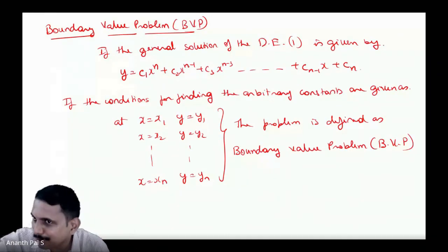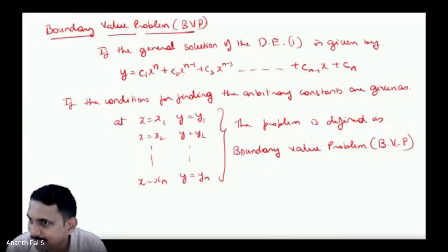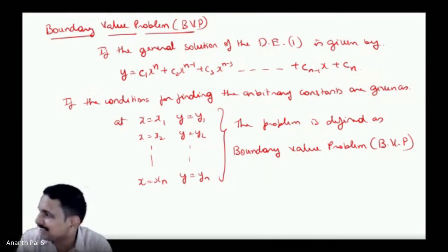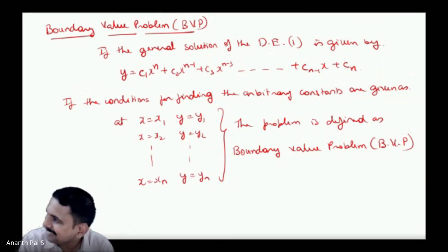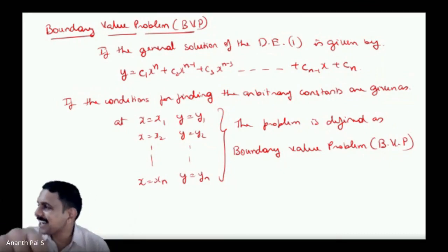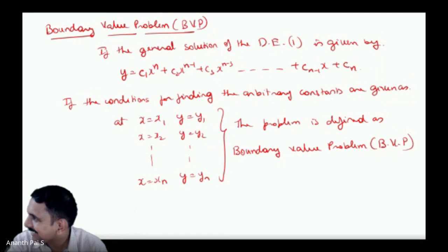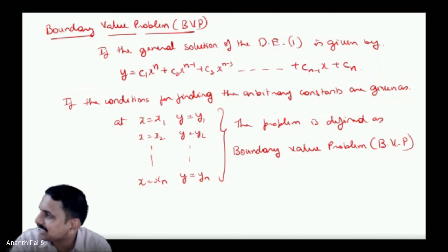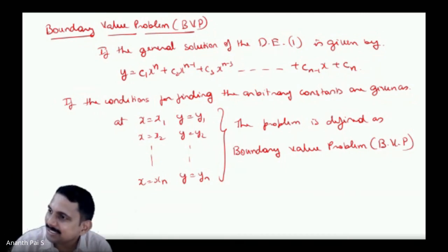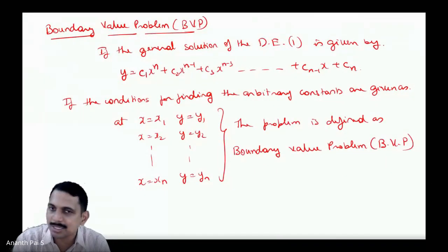If you go to AutoCAD, have you gone to AutoCAD? In a circle, you have 9 types of defining a circle. Center and two sides of a diameter, you define it. Center and radius you can define. Then tangent, tangent, radius. Point and a center, point and a tangent, something like that. There are 9 ways. I remember that because I used to do it on the board.